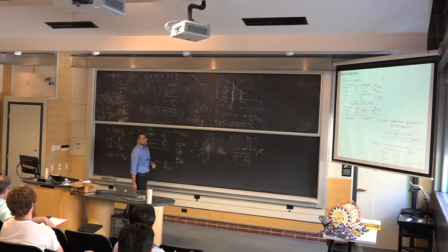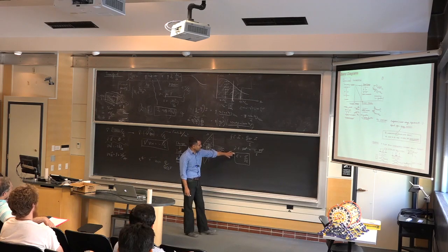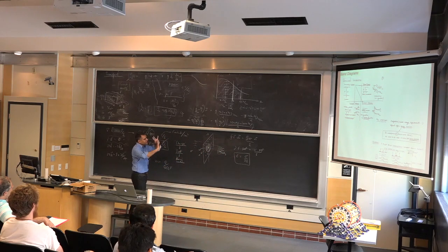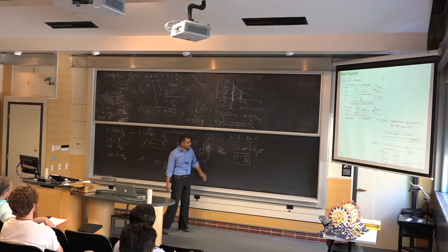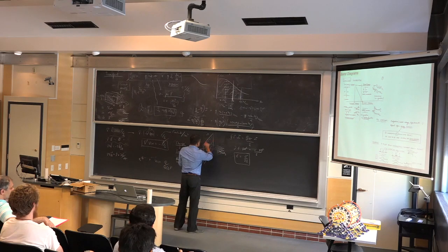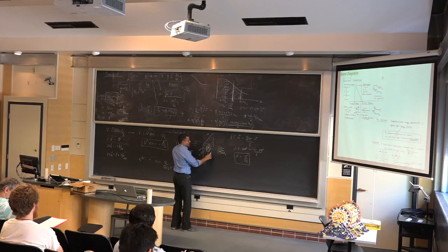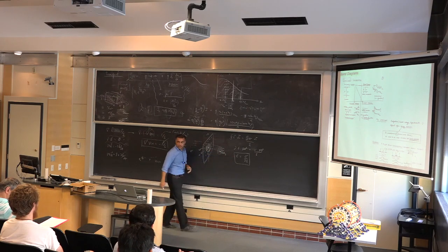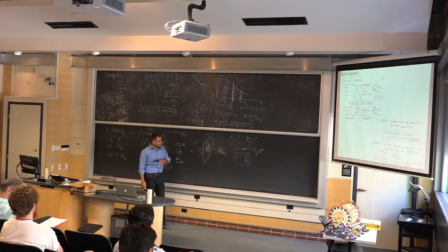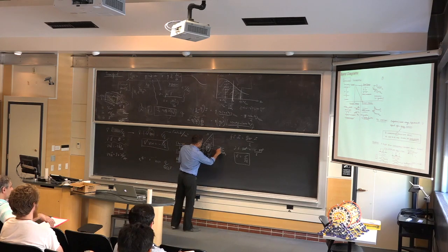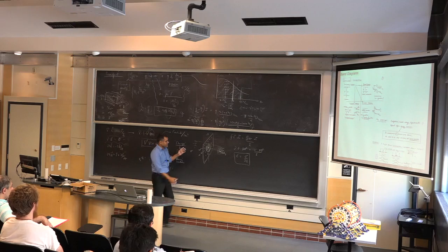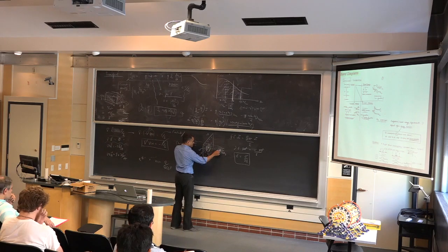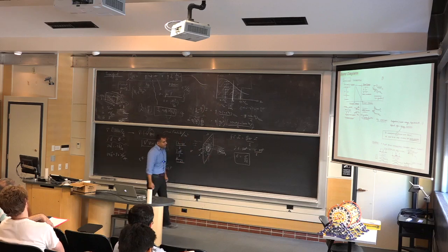Let me put it this way. This is actually probably, in energy band diagrams and other things, one of the most important results. It's the simplest one, but it's very, very important. So if you understand this, it will take you very, very far. Schottky diodes, PN junctions, bipolars, FETs. It's a very simple relation, but what it's saying is, look, if I had a positive sheet charge, no matter how far I am from it, my field is always the same. The field is not changing. It's very weird if you think about it, but this is actually correct. And the field is the sheet charge density divided by twice the dielectric constant, and if I have positive charge, it's pointing away from the sheet, and if I have negative charge, it's pointing towards the sheet. So that's all it's saying.